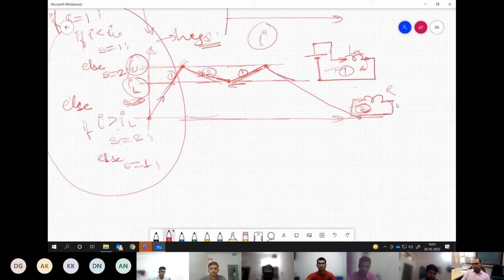This is simply shorted. That means it is at the mercy of the resistance of the coil. If resistance is too small, let's say tending to 0, then it may take a lot of time to discharge. Which means when we have to switch off the coil, it may not come back to 0 for a very long time, which is not correct actually.